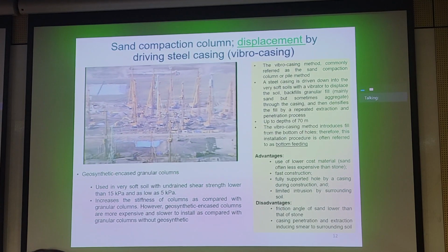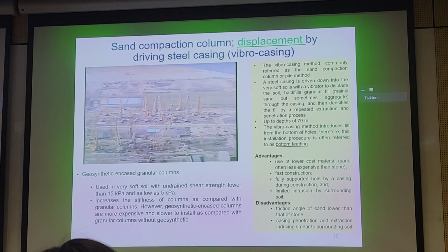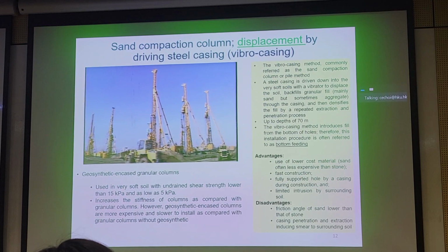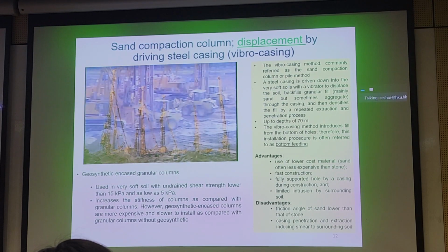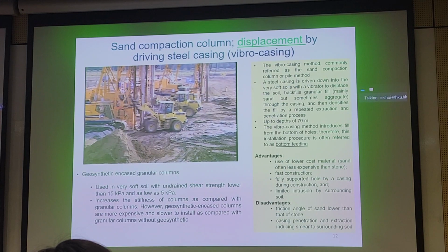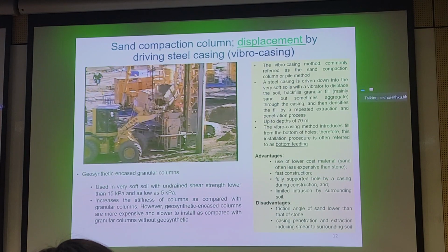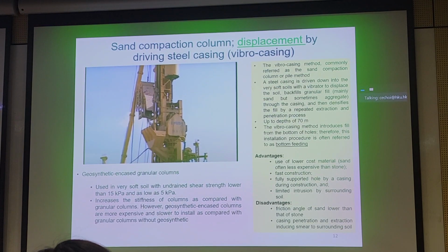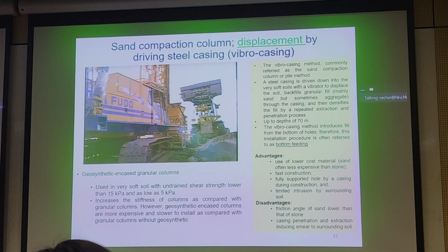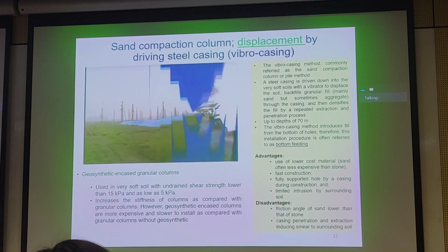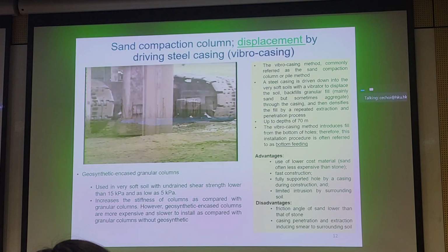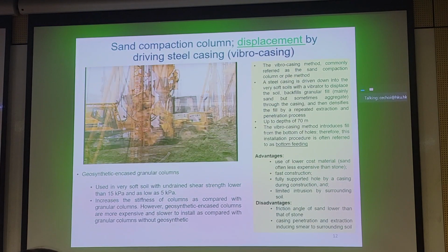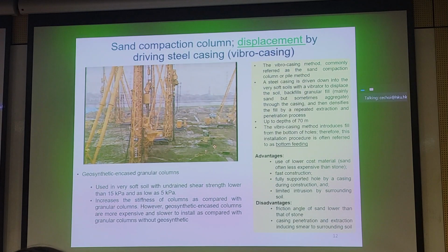Repeatedly driven into the ground, withdrawn, and driven down again. By using the casing as well, you have lots of control about trying to line the casing with geosynthetics as you put it down. So when you retract the casing, you can have a lot more lateral thrust resistance with any geosynthetic. So these columns are very similar to the other methods we looked at, except you have a casing to protect your hole. In this case, you can have top feeding, dry top feeding as well.